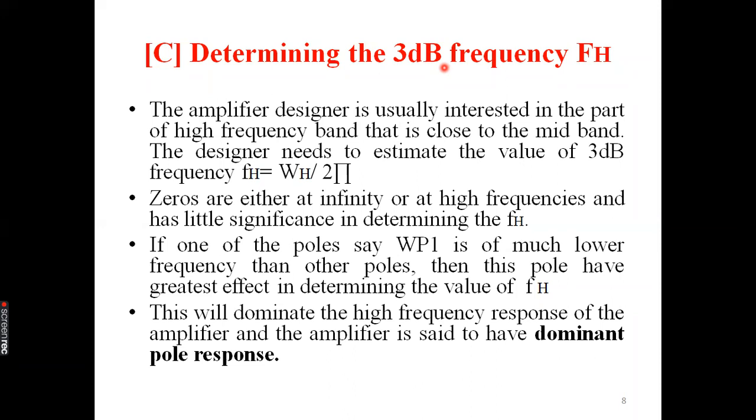Okay, so it is highly desirable to know the cutoff frequency of the amplifier. Why do we want to know this cutoff frequency fH? Because only then will we be able to confine our input signal within these particular frequencies. Otherwise, we will give our signal at our own wish at any frequency range, and the amplifier will produce its own response at its own wish, which is not at all desirable for our load, isn't it?